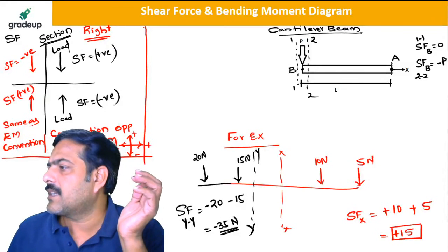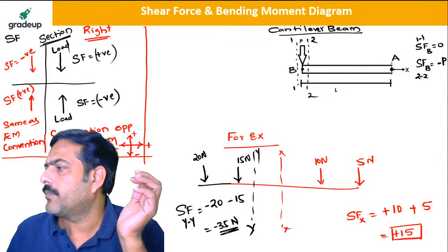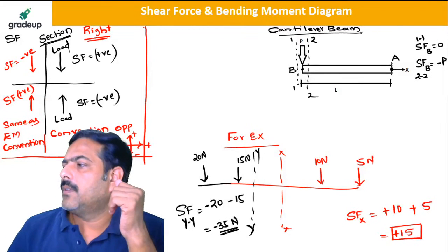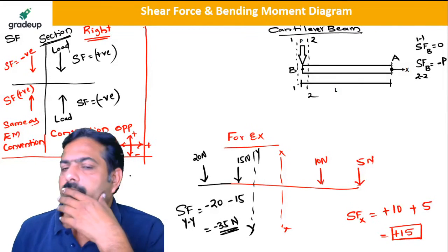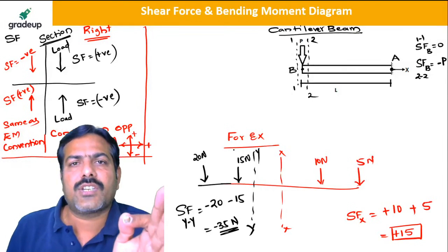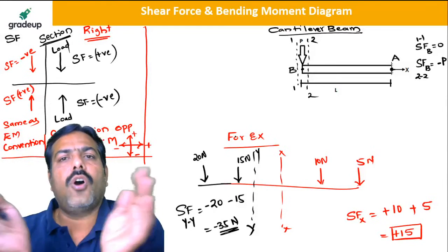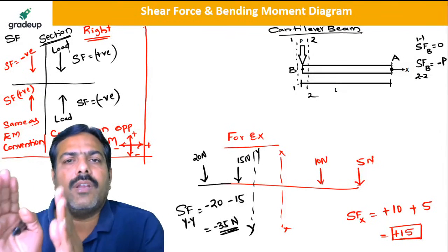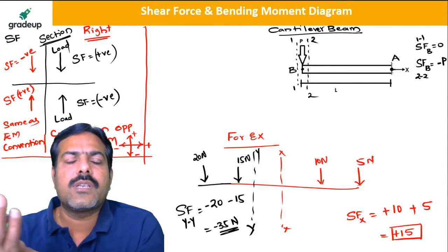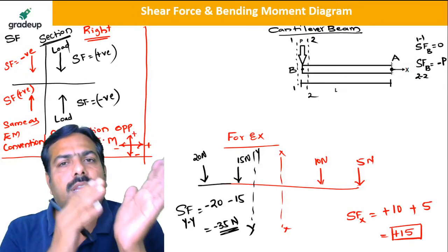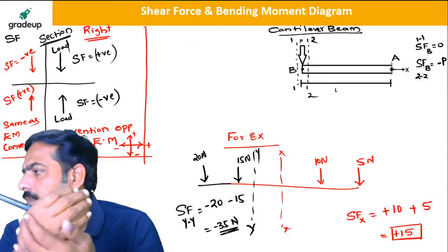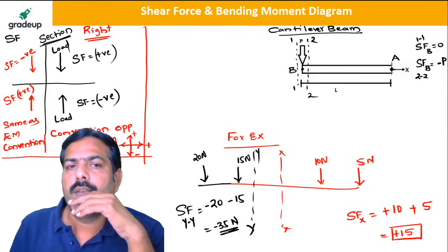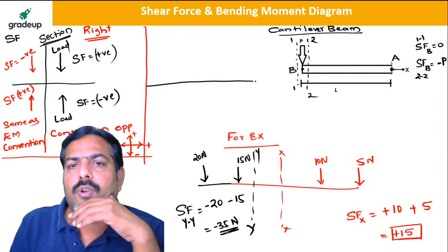Yes, my dear friend, is this clear to all of you? So wherever you take a section, you either solve the right side or the left side. If you solve the right side, whatever is given, the opposite of that is the shear force, and on the left side, whatever is given is the shear force. Clear?